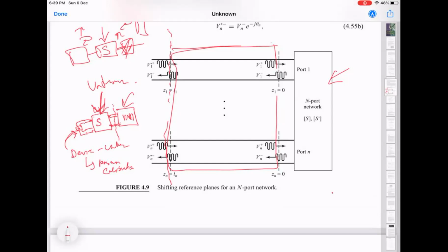So in our experiment, let's say we sometimes change our circuit elements. Let's say this unknown S matrix. If it changes, then the calibration will have to change every time on the VNA? If you are changing the device, then no. But if you are changing this intermediate object, which means that you have changed the wiring, then of course the old calibration will no longer work. The system will still output some answer, but it will not be the correct one. So you will have to redo the calibration if you want to get very precise results.